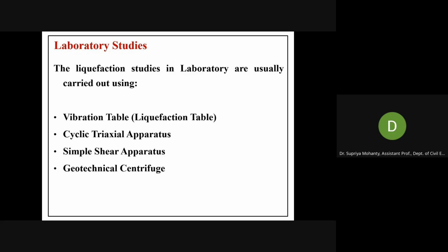And depending on the facility, for lab study there are different facilities, like vibration table, cyclic triaxial test, simple shear and geotechnical centrifuge, for creating liquefaction by vibration, and you can examine the liquefaction behavior of the soil sample.